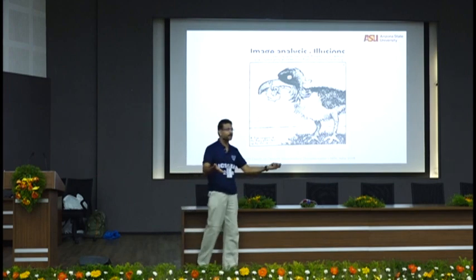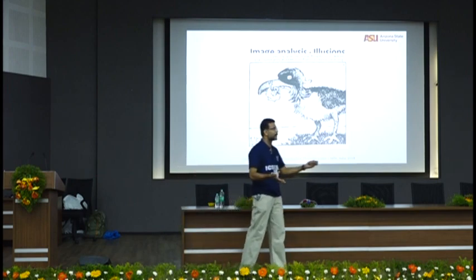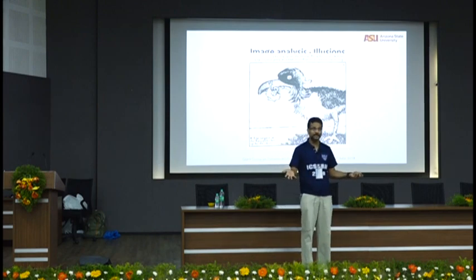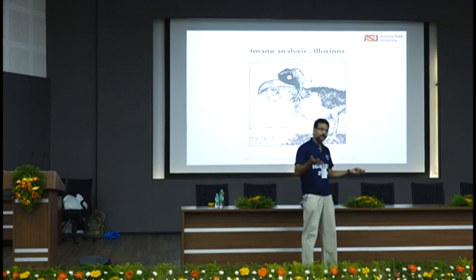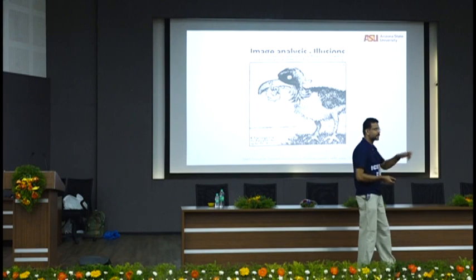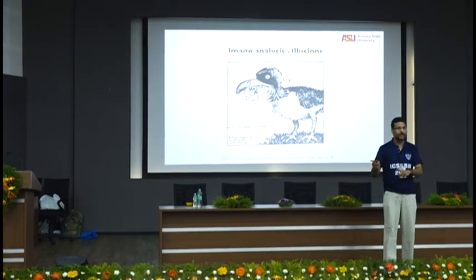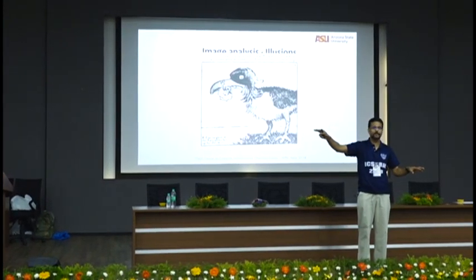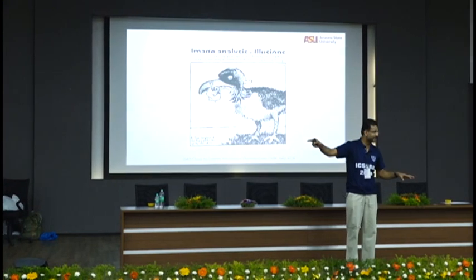Somebody comes and says, my concrete is cracking, my concrete is not reactive, my concrete is not setting. You want to find out why it is. Most of the time you look at SEMs to understand what has formed so that you can solve a problem. If there is no problem in a bridge or a road that you've created, you don't waste time doing an SEM.